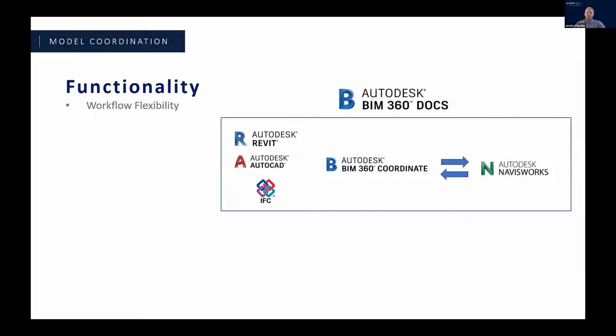For example, if your team is all working inside of a BIM 360 Docs hub and your data is already there, maybe you've got cloud-hosted Revit models or work shared models, your CAD files are saved there, you can automate or almost remove that step of having to regularly push or upload data, whether it's to Glue or to a specified coordinate folder location, just by using the automatic features of BIM 360 Coordinate. And again, that's just pulling the data in. You can use the other functionality of Coordinate then on that data as it's updated live, as people are saving files.